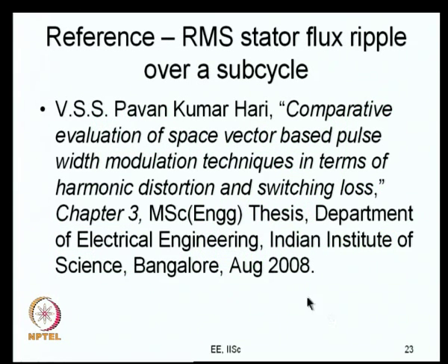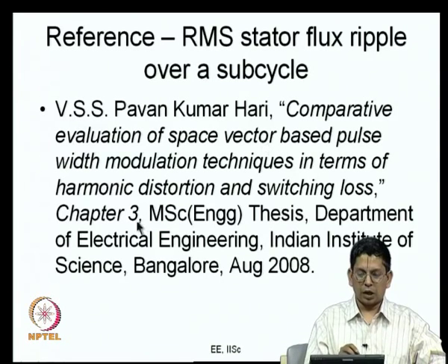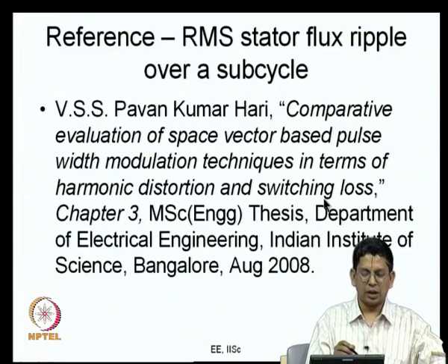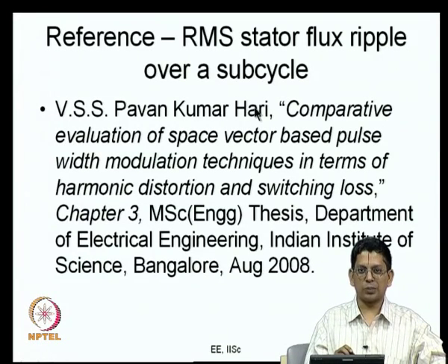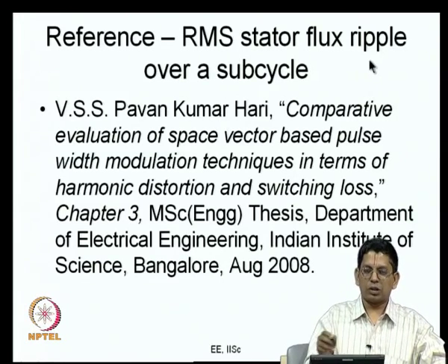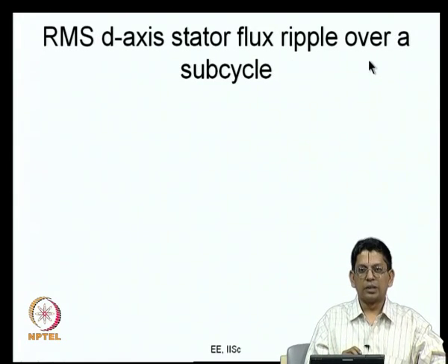You can refer to this MSc engineering thesis by Mr. Pavan Kumar Hari on comparative evaluation of space vector based pulse width modulation techniques in terms of harmonic distortion switching loss. You can particularly look at chapter 3 for this reference, where the question of RMS stator flux ripple over a subcycle is discussed, and particularly the calculations of these kinds of areas. The details of the calculations that I am presenting here are available there with regard to RMS stator flux ripple over a subcycle.